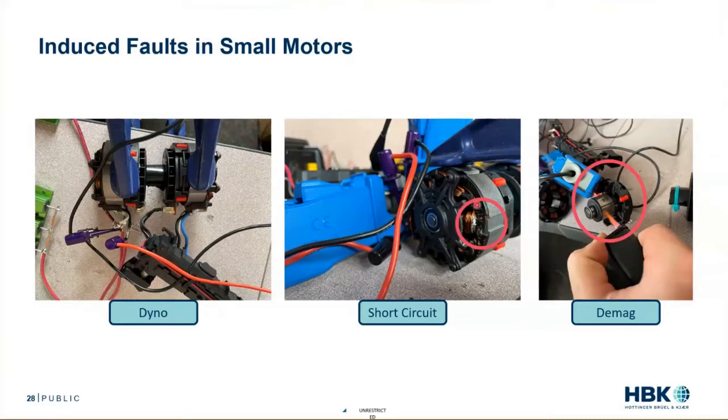In one test, I induced a short circuit fault, and as it looks, I shoved a soldering iron into the winding and I put some solder in there, and that is an induced fault. So that's a little bit of solder and a whole bunch of melting.